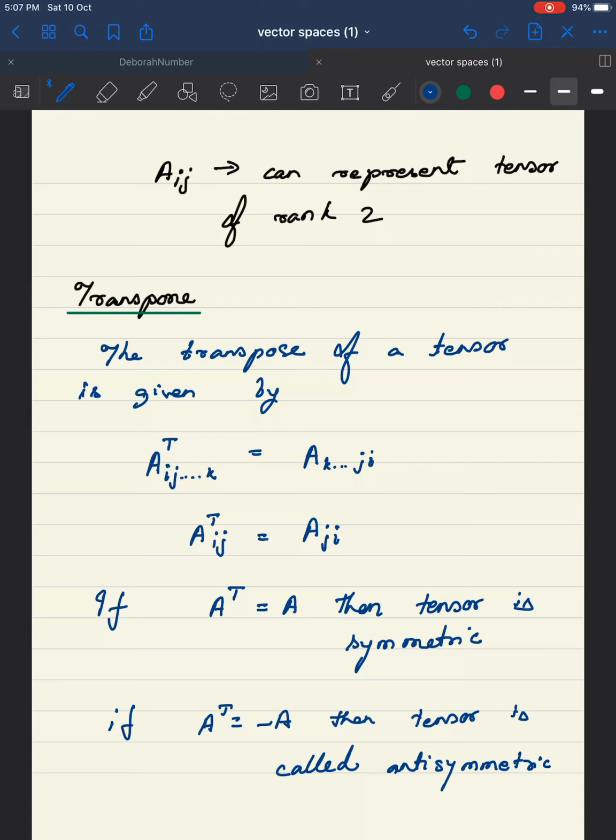Okay, so we will come to this when we look at the stress tensor. We will see that the stress tensor is actually symmetric. So even if you take a transpose, you end up getting the same values. The stress tensor is symmetric for certain types of materials, which includes Newtonian fluids, so water and air are all fluids such that the stress tensor is symmetric. But that need not be. There are other types of fluids for which the stress tensor is not necessarily symmetric. Of course, that does not fall within the purview of this particular class, but there are fluids like that as well.